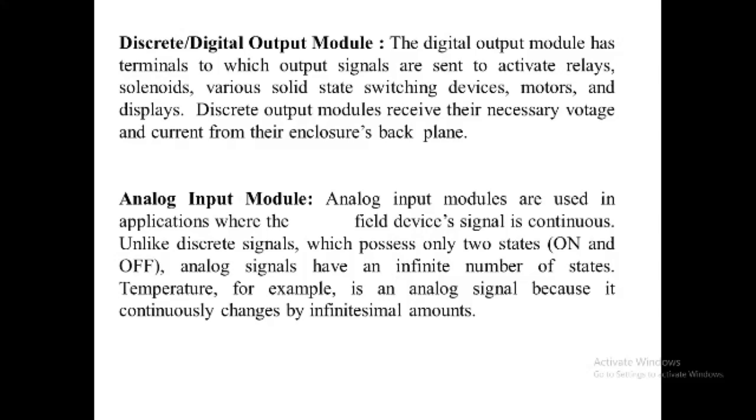This DC interface controls discrete DC loads by switching them on and off. The functional operation of a DC output is very similar to that of the AC output. And here the transistors are also susceptible to excessive applied voltage and a large surge current, which can cause over dissipation and short circuit conditions.